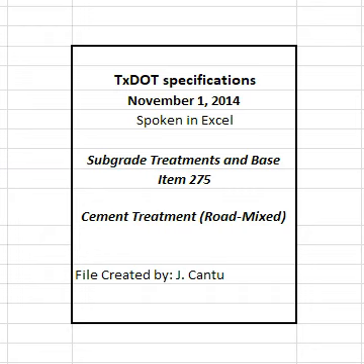4.7 Microcracking. When shown on the plans, maintain moisture content of the finished cement-treated base for a period of 24 to 48 hours. During this time, but not sooner than 24 hours, roll the finished course with a vibratory roller to induce microcracking. The vibratory roller must be in accordance with Item 210, Rolling, with a static weight equal to or more than 12 tons and the vibratory drum must be not less than 20 inches wide.